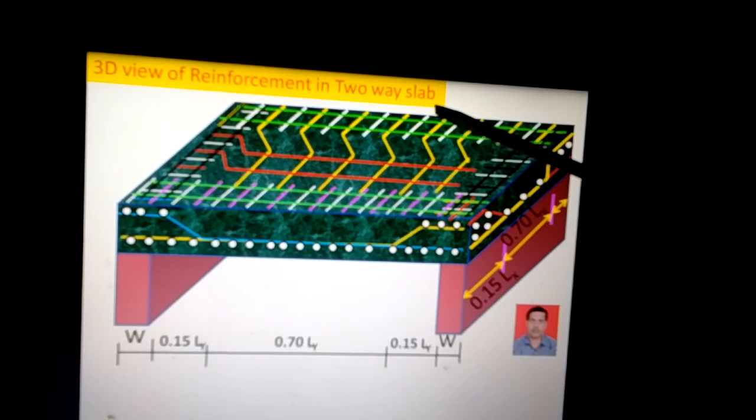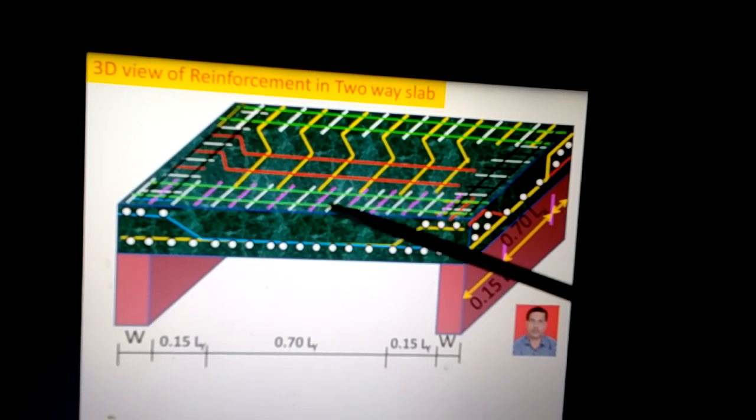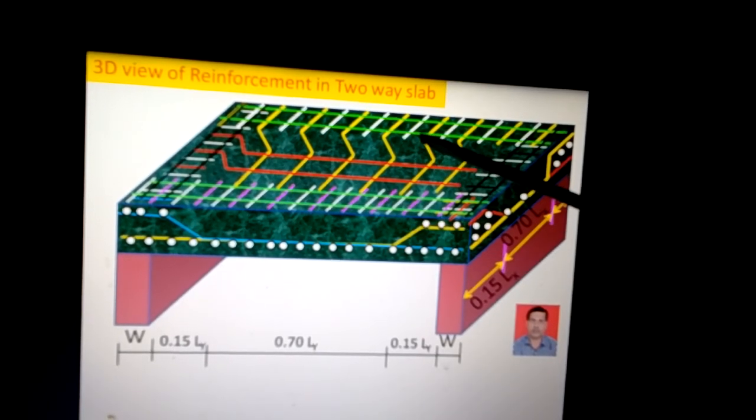This gives us a better understanding of the slab reinforcement, the placing of the reinforcement, the dimensions, where the bent up should start in case of a simply supported slab, and how it should be tied, and what precautions are to be taken for safe casting of the slab. The proper location of the reinforcement needs to be ensured by fixing them at all junctions.